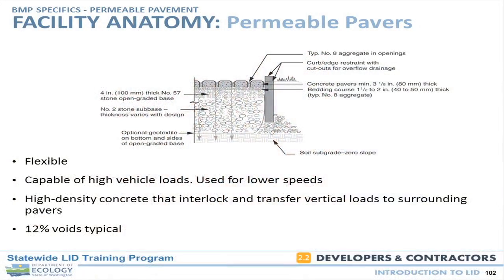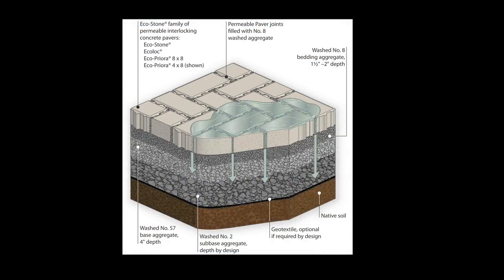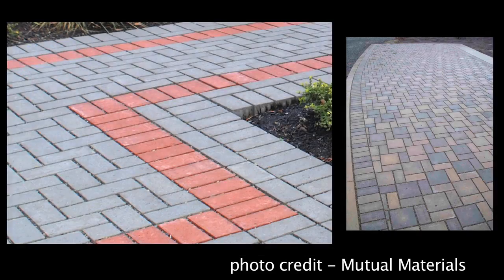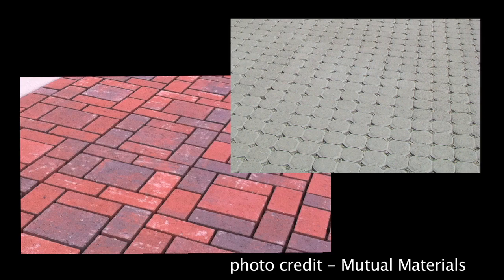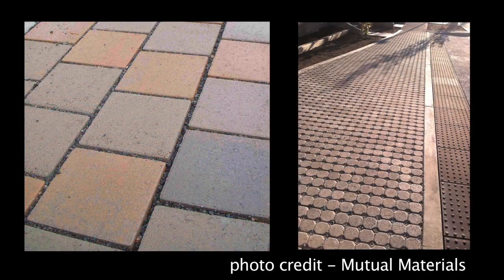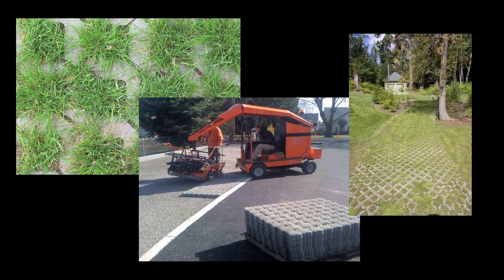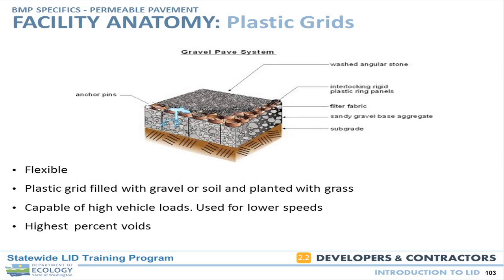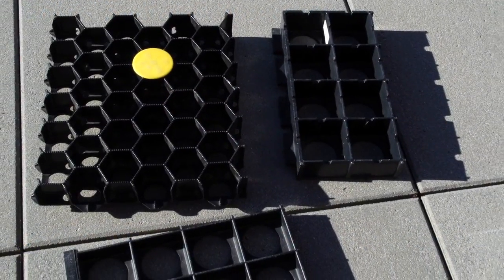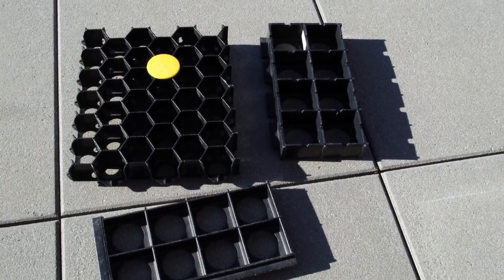In terms of the unit pavers, these are a flexible pavement. They interlock just like a traditional unit paver system. Good edge restraint, making sure that it stays put. There are drainage voids provided, and then there's a dozen at least different shapes of porous pavers out there. The plastic grid system, all these sections have different thicknesses, different price points, different shapes, but they all essentially achieve the same function of containing the material.